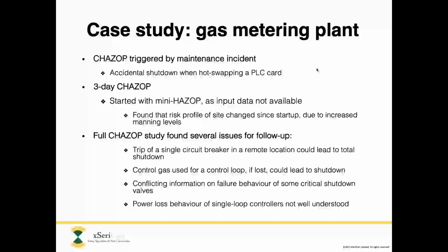Okay, we're almost at the end of what I wanted to cover. Let me give you some specific examples. So let's say we're studying functional area DCS, and we're looking at failure class software. So we're looking at software issues. And when we work down our checklist, we find there is a question in the checklist that says, what if the application software fails? In other words, there's a bug in it, and that bug results in a false zero output on the I/O cards.